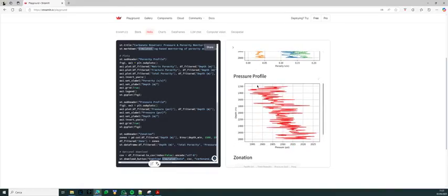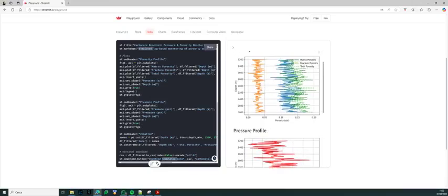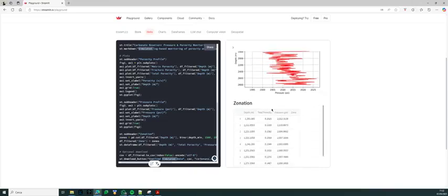And so we also have the pressure profile that was recorded during this interval of years, starting from 1995 to 2025. You can see that in this case we have a trend that is not well underlined, but we have a trend of increasing pressure, because it's clear that when we make extraction for a long period we can also have compaction and other diagenetic phenomena.